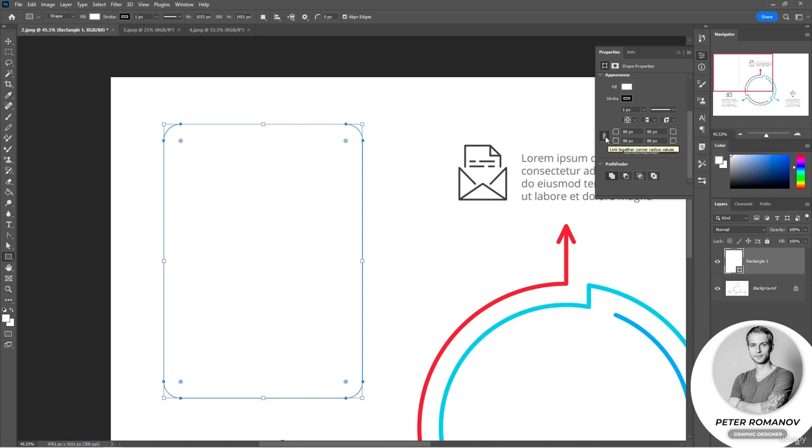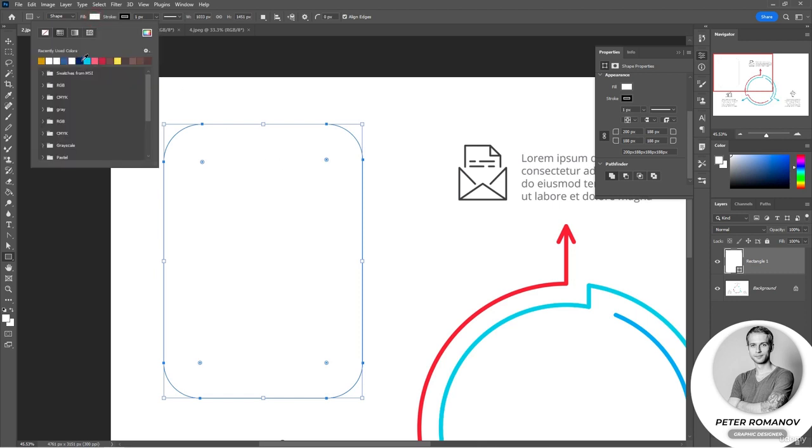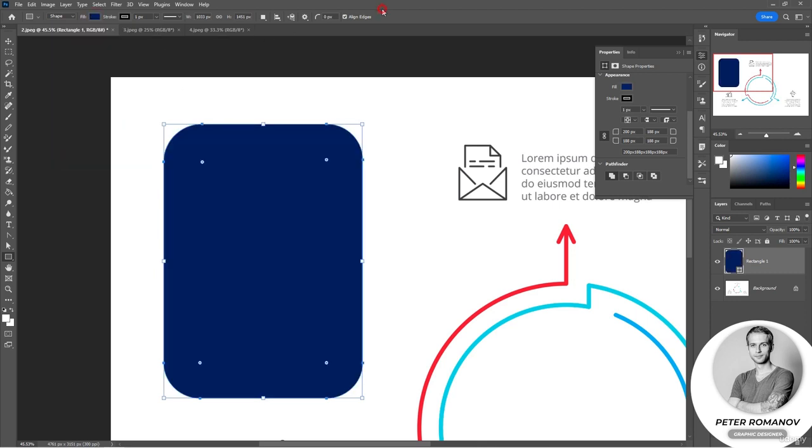And if I now click on this lock here, set 100 pixels and press enter, then you see right away that my corner has rounded much more. But at the same time, all the other corners have rounded too. By the way, the advantage of this palette is that you can edit the shape after it is created at any time. You just need to select the desired layer, open the Properties palette, and here you can change different parameters.